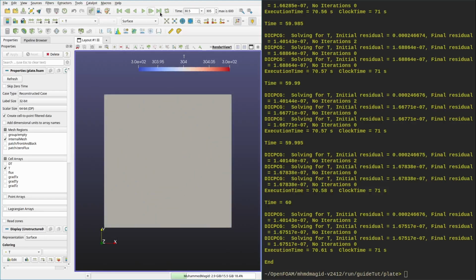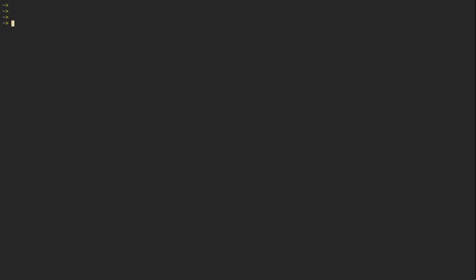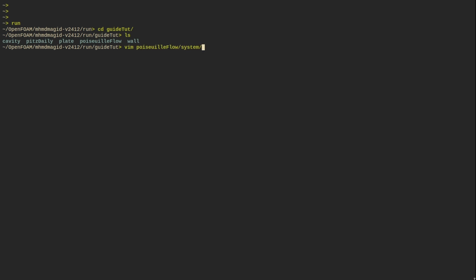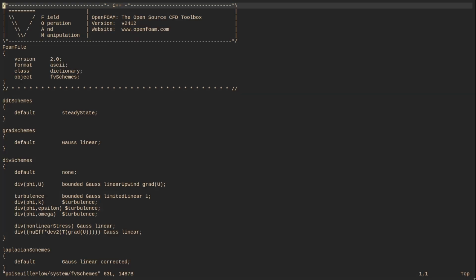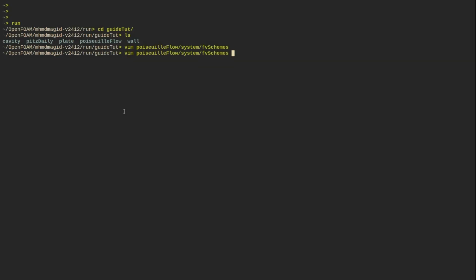Now that we have covered the basics of initial conditions, I think it's enough for this tutorial. However, there is one important concept I want to clarify, which is initial conditions in steady-state simulations. Take the Poisson flow we simulated in the previous videos as an example. While this is a steady-state simulation, we still defined initial conditions for the system. So you might be wondering, what exactly do we mean by initial conditions in this context?